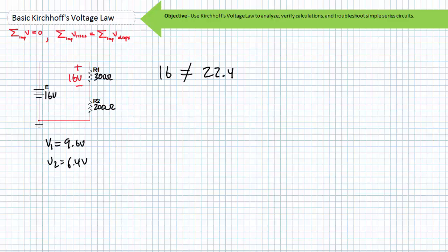Before we move on to any additionally valid answers to this quandary, pause momentarily to consider the magnitude of the source voltage necessary to induce a 16-volt drop across a 300 ohm resistor in series with a 200 ohm resistor. Again, this hypothetical scenario is an excellent opportunity for you to apply Ohm's law, basic series circuit properties, and KVL. Pause the lecture if you want to take a stab at this. If you're correct, you should find a source voltage of approximately 26.7 volts would do the trick: 16 volts being dropped across the 300 ohm resistor and 10.7 volts being dropped across the 200 ohm resistor.